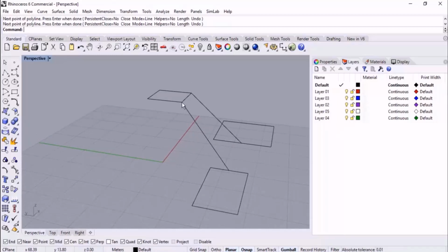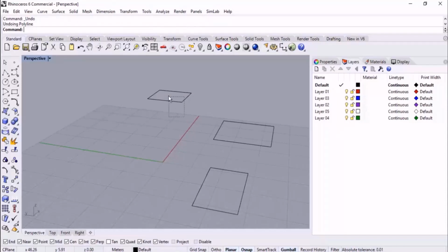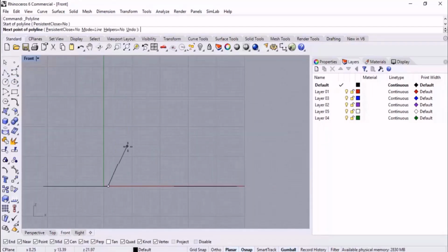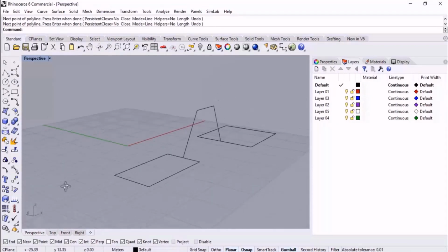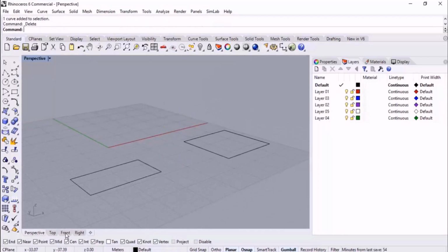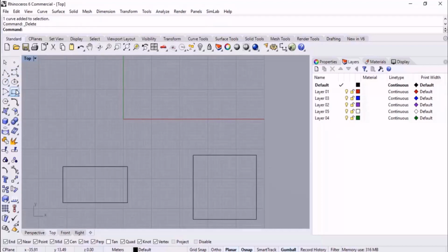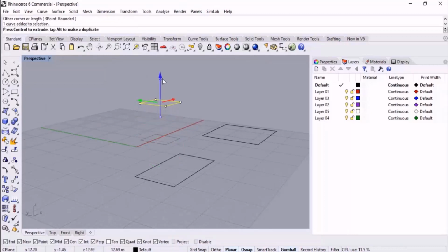Since a condition is required while we are using planar to place all of the points in the same plane, which is not using snaps in sketching the lines. In other words, we should use either planar or the snaps. I mean, if I delete this rectangle and then I start sketching from the midpoint, the planar is enabled. Check this out, I can have this gate without any problem. Guys, let's check it out. We haven't used snap. But if we want to use another object in the process of sketching and then snap the points to it, then in this situation planar is not effective.